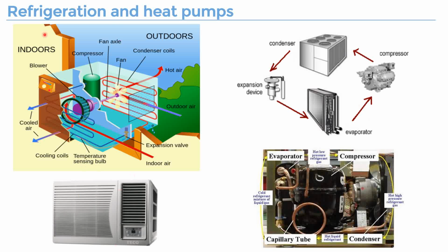And if you could understand the principles inside here, you could also apply that into some much larger commercial products, like hotels or hospitals that are basically using the same, but using many evaporators in each room connected together, and get connected to the compressor, go to the condenser, expansion valve device, and go back again. So that's a larger cycle. But for the very basic or simple example, the old air conditioner, you can see it's still using the evaporator going through compressor, condenser, and expansion device.